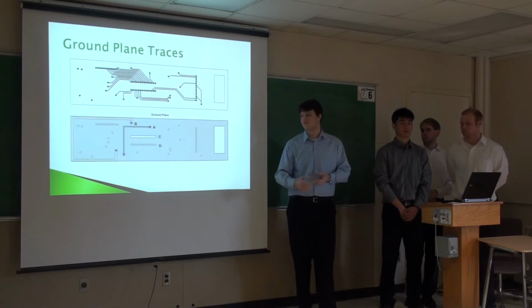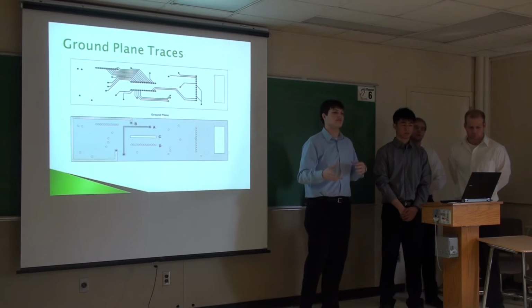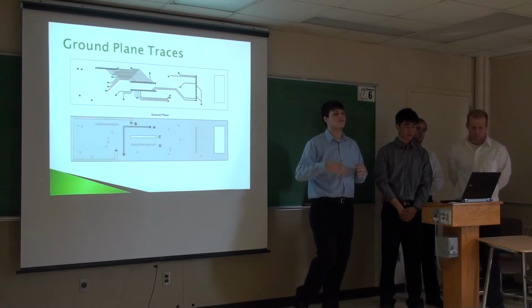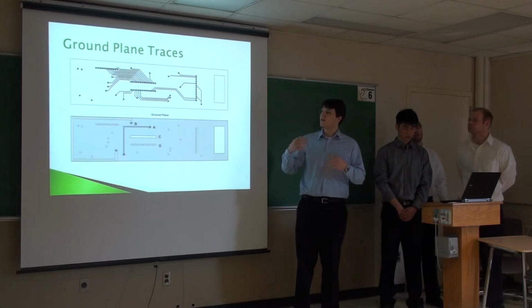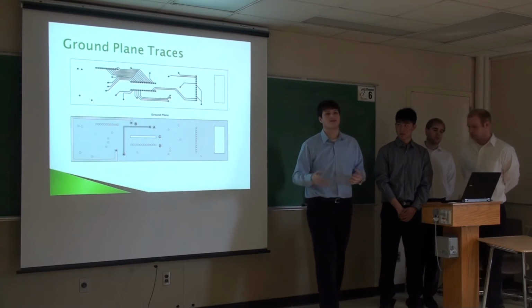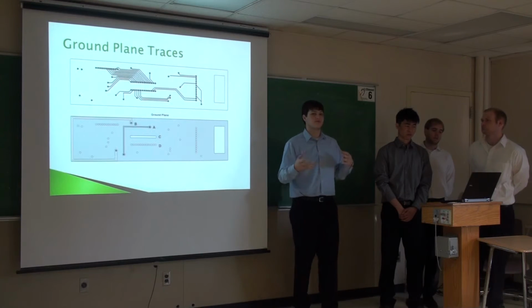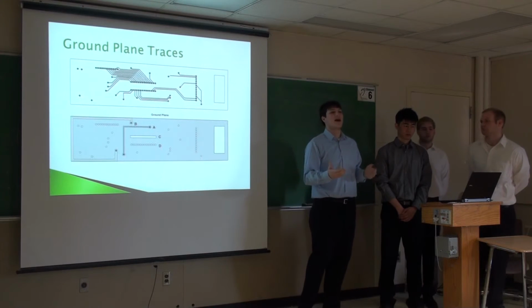So a much better option would be something more like D, where you cut individual holes for each of the pins, so you're still isolating to make sure they're not all grounded, but current can flow through there. So it greatly decreases the impedance in the ground plane. Now, if you have to make traces, which is something you shouldn't do in general, you don't want to make traces in the ground plane, you want to make sure that when you do, you don't greatly increase the impedance in the ground plane. So A cuts the board into two halves, left and right.